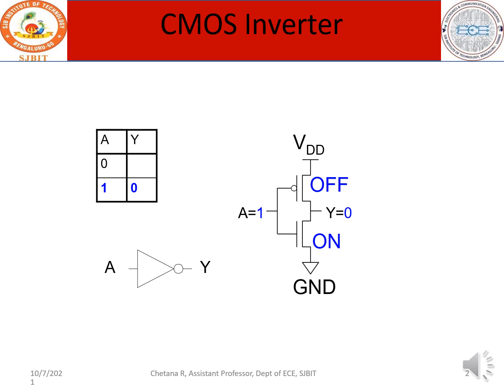And in an inverter, this is how the connection is given. They are neither in series nor in parallel. That is the reason I told you in my previous video that a CMOS inverter is a combination of NMOS and PMOS. What combination is it? It is not in series. So the two gates are connected together and you have a single input. The gate of PMOS and gate of NMOS are connected together and together they form a single input because input is always given at the gate terminal.